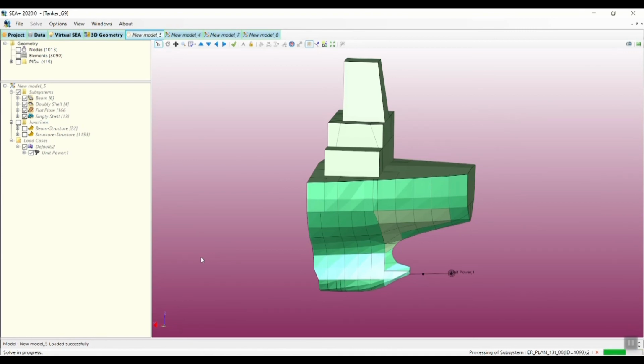In this case, it takes time because we have to scroll all subsystems, compute all modal densities and all mobilities and so on, all SEA parameters, and then it enters the processing of coupling. So you see it's very fast on the bottom and full line, because junction calculation is highly parallelized.